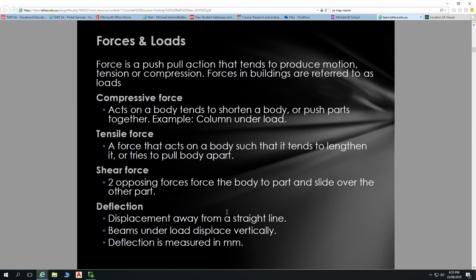And we leave that side abutting the wall, but not fixed. So that cornice can go up and down slightly as well. Because if we fix the cornice to both sides like that, and we get trusses moving up and down slightly, that will break and it will tear off a bit of plasterboard and whatnot and look terrible. If you at least paint to the underside of that and you get that millimetre or so of movement, you won't see it. So building elements deflect, and we have to design to cater for that.